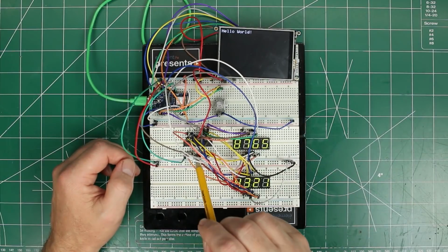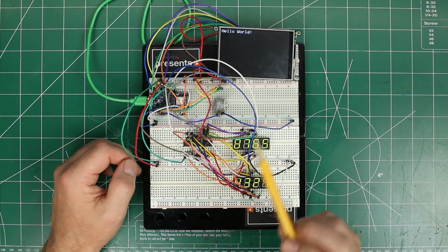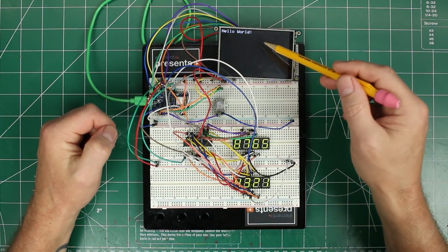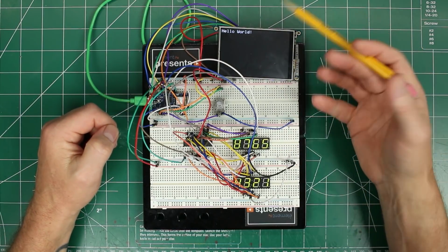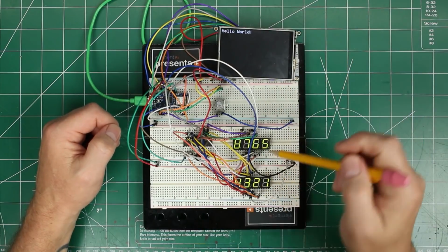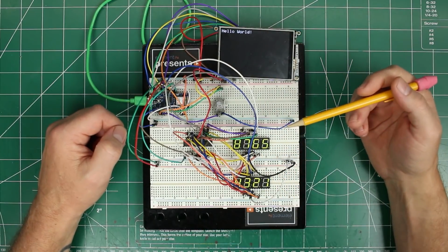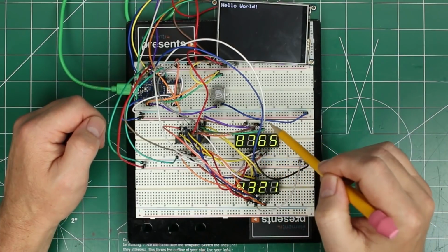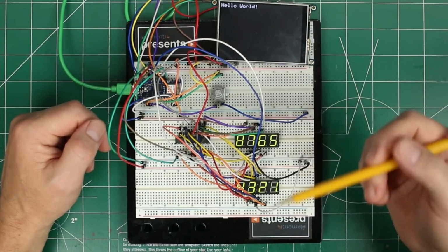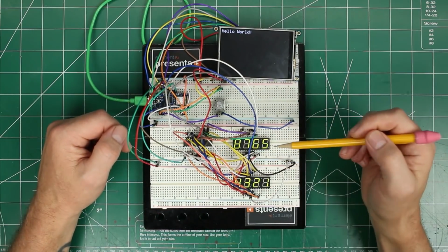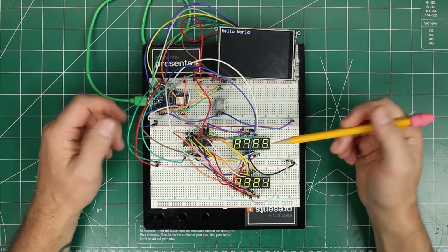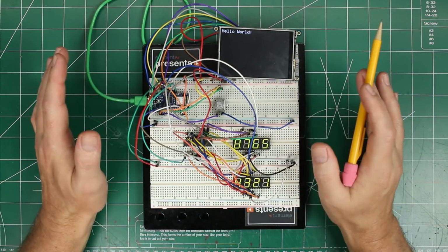It is connected via SPI as well, and I had to do software SPI because the software for this doesn't let go, and it just got complicated, but it's totally fast enough to run on software SPI. It's got a pin for each digit, and then it's got pins for each of the segments. It sends it once when it writes it, and then this IC handles all of the refreshing at the right time. So now it just works perfectly, and I'm super happy.